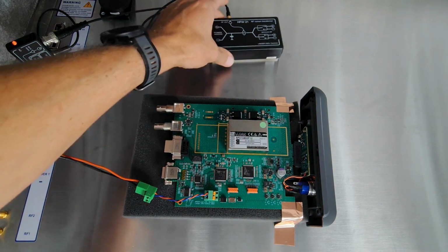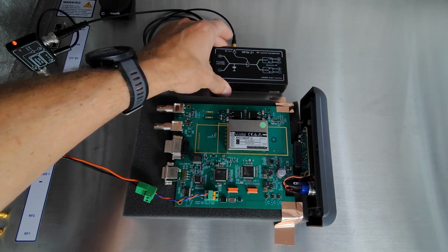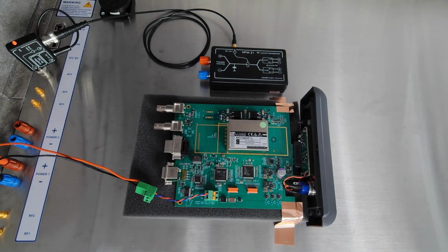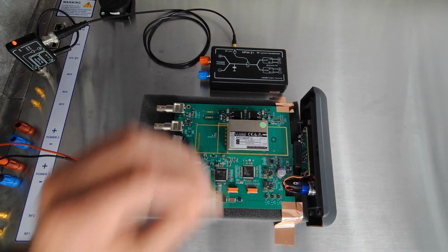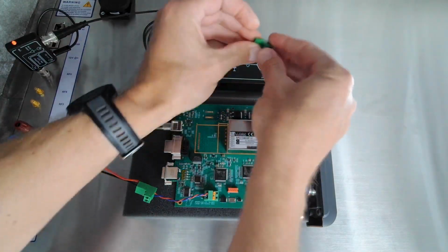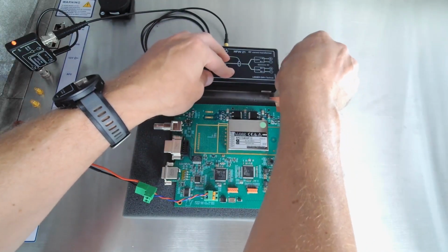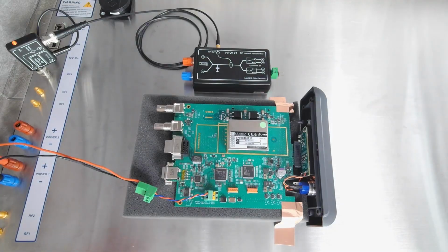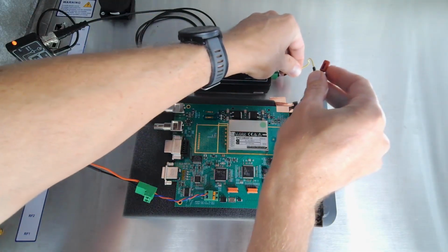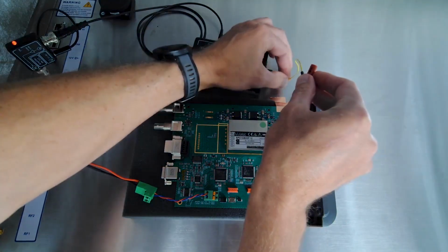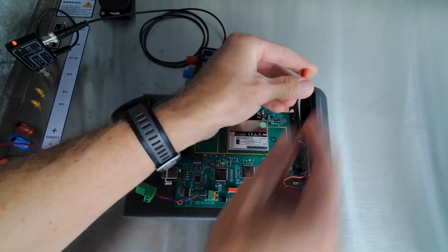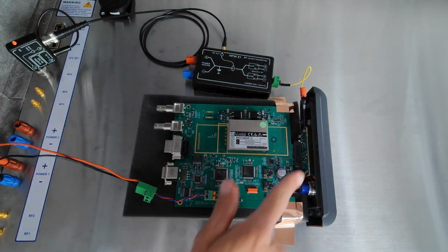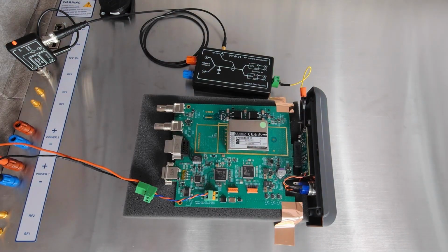Now I have to connect our RF current transformer to the ground of the front PCB. For this I have here such a small connector. This I bring here also to the common mode input. And now I use also one of these cables here to connect it to the ground of the front panel board.